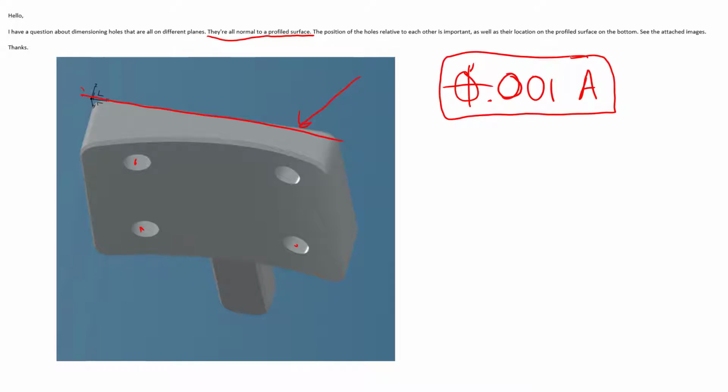Let's say like this. Now, if we had datums B and C, if they had to be positioned from the walls in a tight way, I'd probably do that in this specific case, maybe to this surface and that surface. Let's say that we had B and C on here as well. B being the plane on the side here, and then maybe C being this plane, or maybe you have another feature that's more important to dimension to. But let's just assume, for simplicity's sake, that we're doing this with A as the primary datum, A being this flat top surface, something that we can pull a direct plane from.